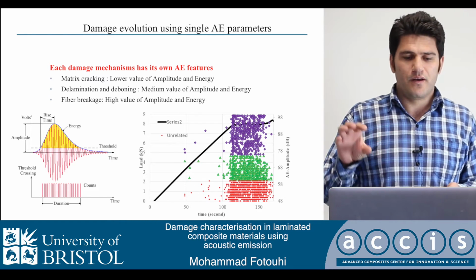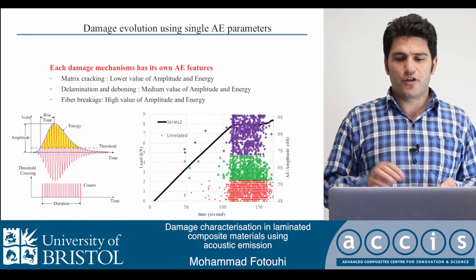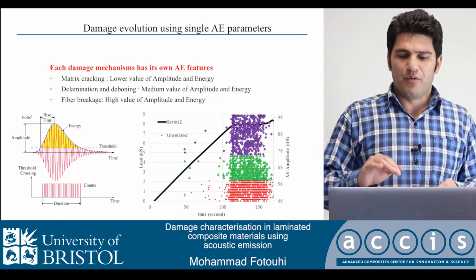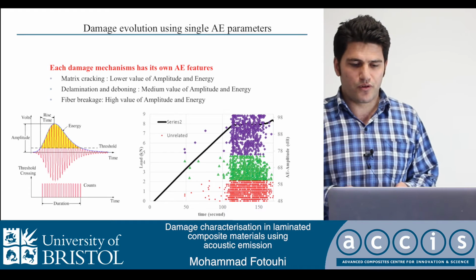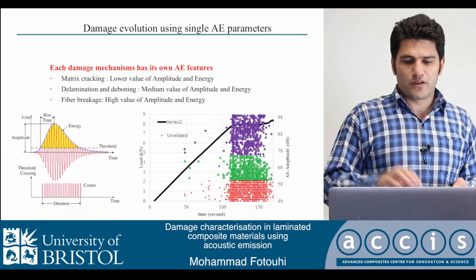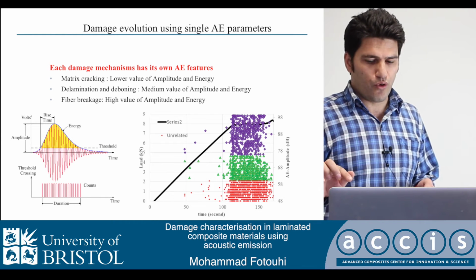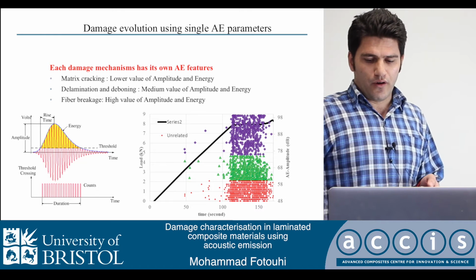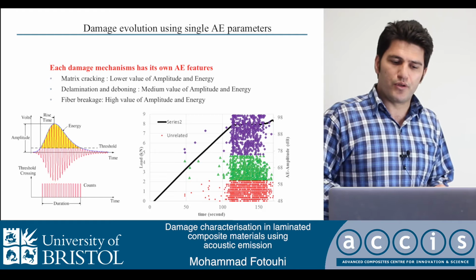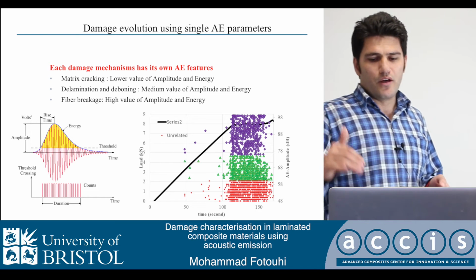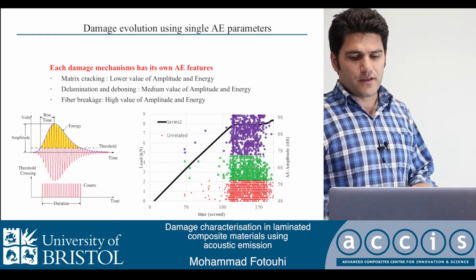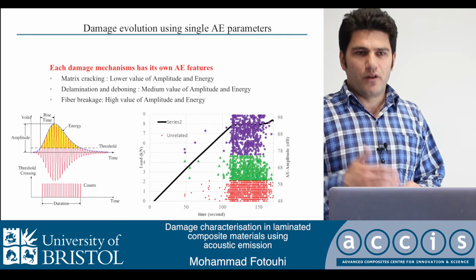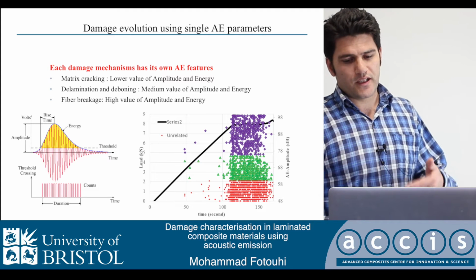Then we used this simple classification, and as you see from the pictures, we separated the signals based on this criteria. There's a black line which is related to load, and we have time here, and on the other axis it's AE amplitude, and we could separate them using this criteria. This is a simple way that we used, and I want to explain some more developed methods that we use to characterize these damage mechanisms.